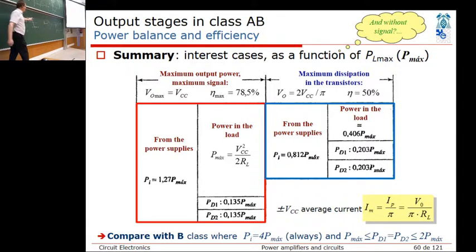All right, and then of course, let's see. The worst case happens when you are saturating this one on that highest power dissipation on your transistor. So, meaning you are overdriving the pre-amplifier states, not the power amplifier.